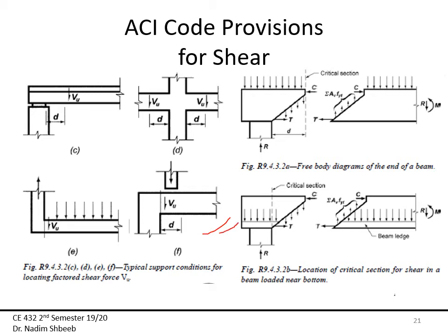Here's what I meant about having the load next to the bottom of the beam. In this case, my critical section will be at the face of the support.